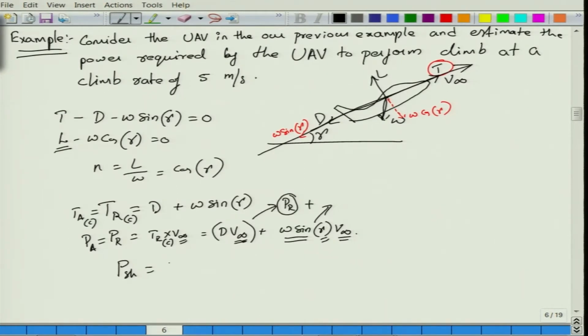So, now the shaft power PSH that the engine has to deliver or make available for the propeller or the aircraft is the power available, or the power required by the system, upon shaft propeller efficiency, right. From the above step, this is like the second step, and from step 3 we will be able to find out the power required, or the power available, that needs to be made available by the propeller power plant for the aircraft to fly at this particular velocity V infinity.